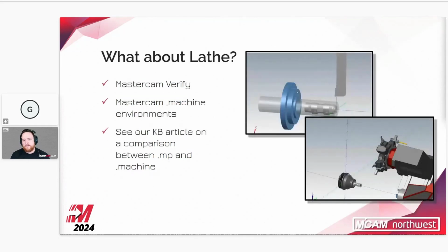So before we go any farther, I do want to address lathe because lathe is not going to be covered in today's presentation. Mastercam lathe is pretty limited in what it can do for simulation. And if you have a traditional MP post for your lathe, you will be limited to only using Mastercam Verify. This works, and especially if you're just doing turning only with no milling, that could actually be just fine. I don't really see a problem with that.